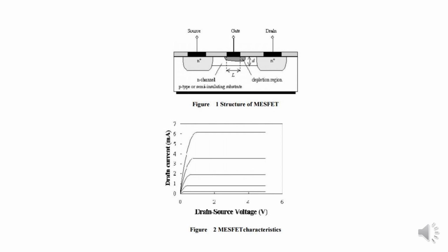And the production MESFETs are operated up to approximately 45 GHz and are commonly used for microwave frequency communication and on radar. From a digital circuit design view, it is increasingly difficult to use MESFETs as the basis for digital integrated circuits as the scale of integration goes on, compared to CMOS silicon-based fabrication.